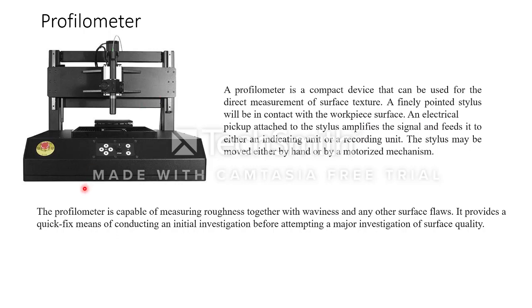Finally, the profilometer is capable of measuring roughness together with waviness and any other surface flaws. Whatever problems the surface has, it can measure the surface texture. It provides a quick means of conducting an initial investigation before attempting a major investigation of the surface quality. That's what I have told you.